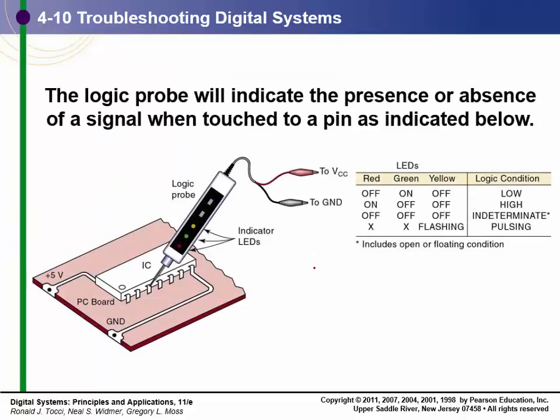Right there. I wish we had a bunch of these on hand, but from what I'm told, we don't have a bunch of these on hand. Yep. I'm used to classes where students were actually required to buy these logic probes. These are the most valuable tools for troubleshooting circuits, because you don't have to bother with the voltmeter to measure every point.